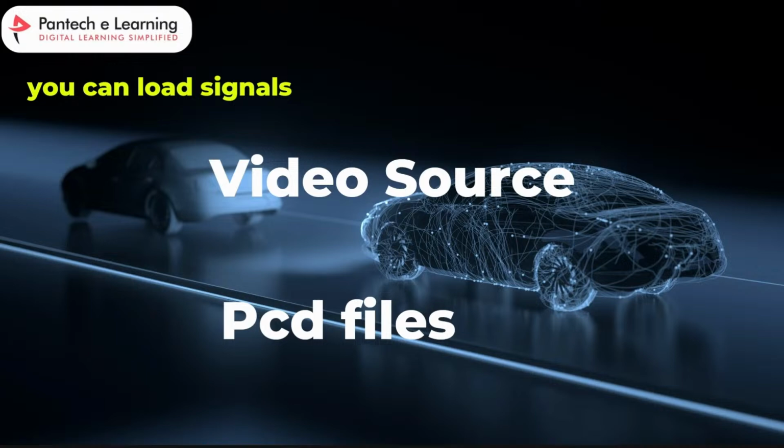Additionally, the Ground Truth Labeler app supports loading sequences from other types of data sources, such as ROS bags. What does that mean? These sources can contain multiple signals, each representing different aspects of the data being captured. For example, in the context of autonomous driving, a ROS bag might include signals from various sensors: LiDAR, radar and camera. So this is how you can load the signals, in the formats of video sources, that is MP4, and PCD files.